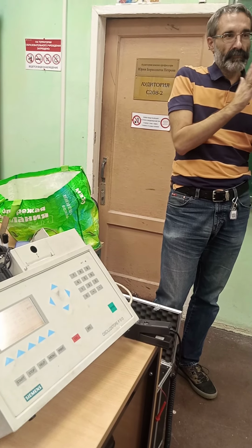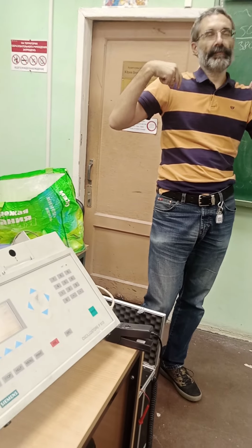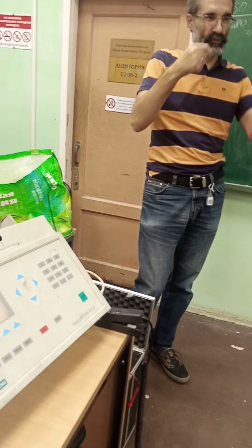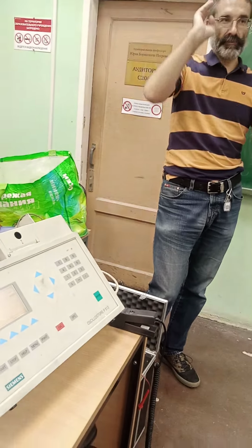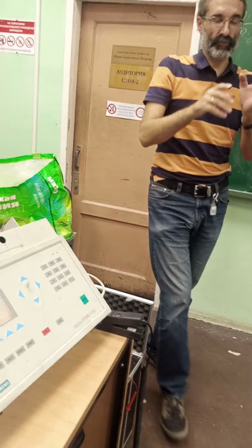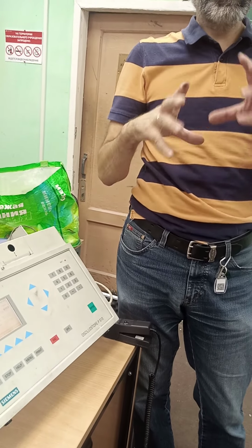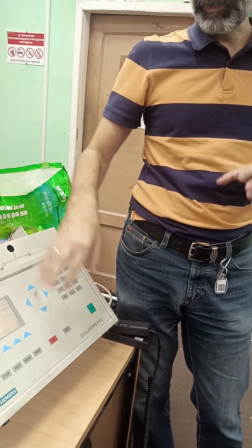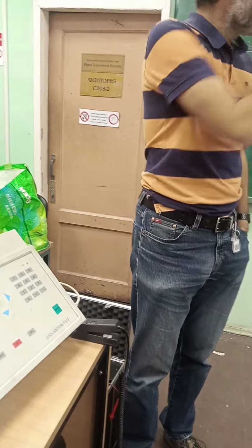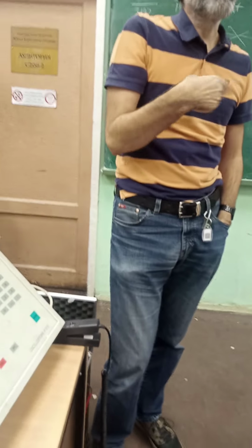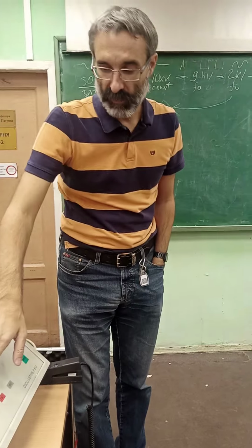In this case, even if this event occurs in the night, we can come in the morning and stop it to be sure that necessary recorded data is stored in memory. So if we don't know how much time we need to wait for the event, we use cyclic.